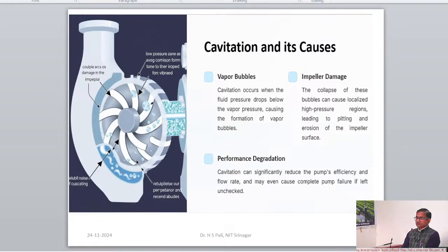You can also get multi-speed circulating pumps, which we'll look at later in this video. When selecting a larger centrifugal pump, as long as our system requirements are on or below the performance line, the pump can be considered. We can potentially use a smaller impeller or variable frequency drive to better suit the requirements. Again, we're going to look at that a little later in this video. For example, the performance curves of 2 large centrifugal pumps are plotted here. We need a flow rate of 30 gallons per minute and a head pressure of 70 feet. That means that pump 2 can't be used, but pump 1 could be.